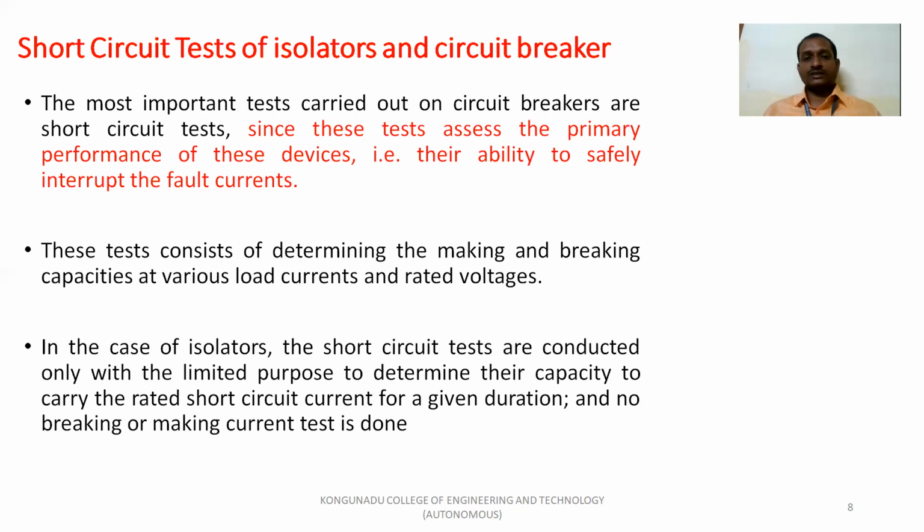In the case of isolators, the short circuit tests are conducted only for a limited purpose: to determine their capacity to carry the rated short circuit current for a given duration. Here, no breaking or making current test is done. We are only going to check the capacity to carry the rated short circuit current for a given duration. This is the aim of the short circuit test. We are not going to do the making and breaking current test.